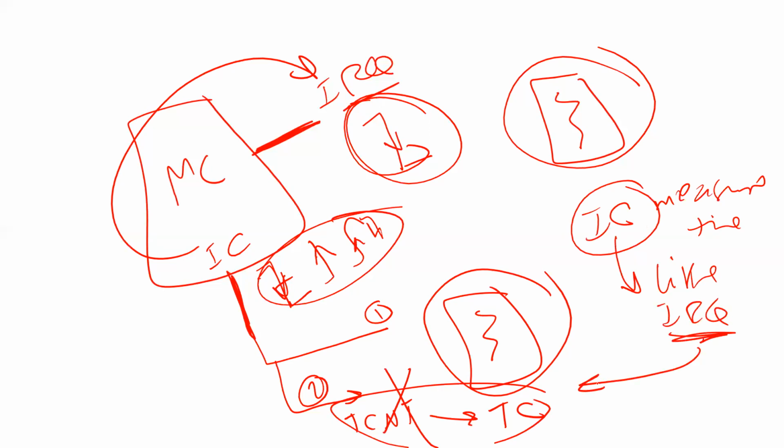So now I don't care about the count. I don't care about the time. All I care about is, similar to IRQ, every time there is a rising or a falling edge, I want to trigger an interrupt. I like input capture even more than IRQ. You know why I like it more? Because it gives us flexibility.